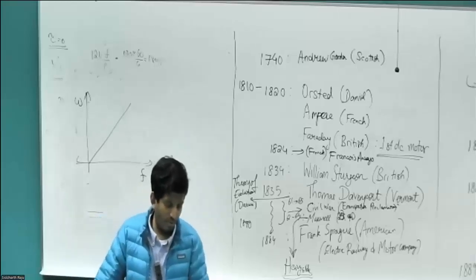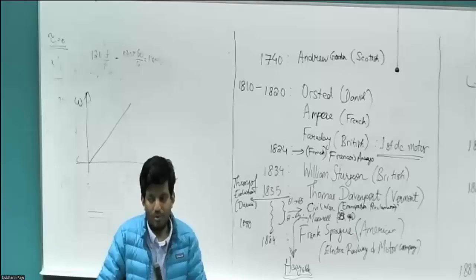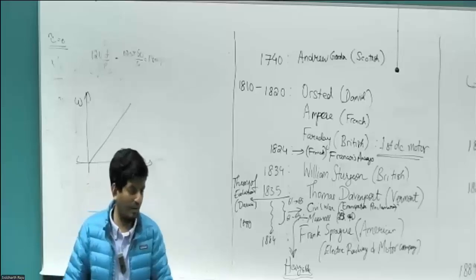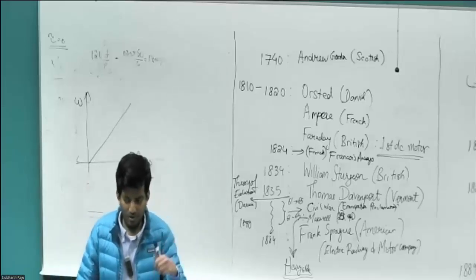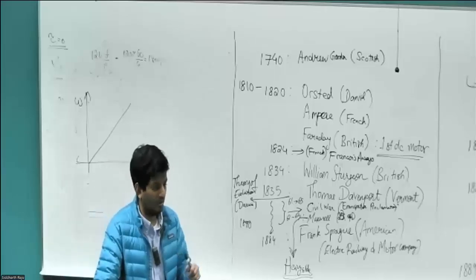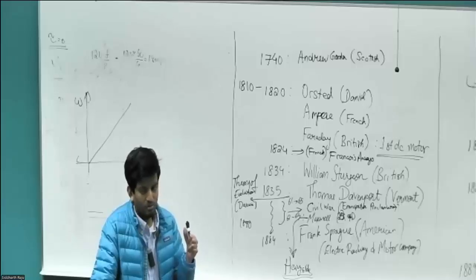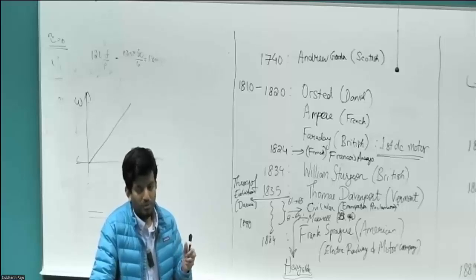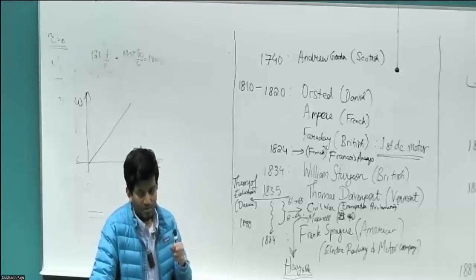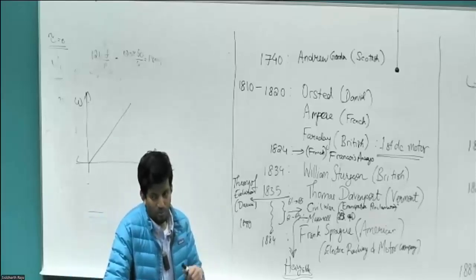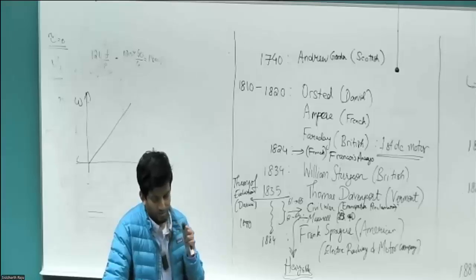But with the advent of power electronics, there is no longer that limitation. Power electronics have become cheap enough that permanent magnet motor with the power electronic converter connected to it can compete with the induction motor. And gradually, many induction motors are getting phased out with permanent magnet motor connected to drive, particularly because it's more efficient, right? It consumes far less power compared to an induction motor. Also, the quality of the power that's being consumed by permanent magnet motor is far better. It's very close to unity power factor if the control is done properly. Right, so these advantages make it very lucrative as we go forward with a more energy efficiency conscious mindset.